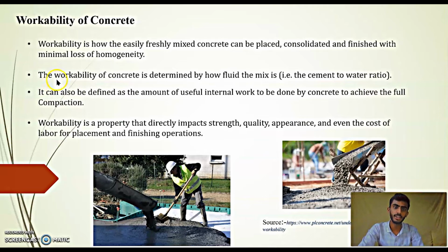The workability of concrete is determined by how fluid the mix is, that is, the water cement ratio. This we will learn in the next slide about the factors affecting the water cement ratio. The next point is that it can also be defined as the amount of useful internal work to be done by concrete to achieve full compaction. It means how the concrete gets compacted without extra compaction is also known as workability.